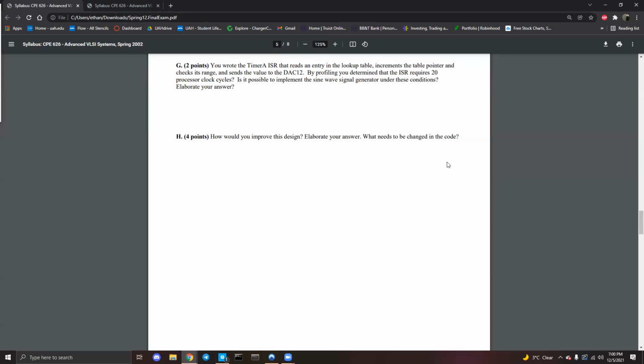You could also implement Nyquist's theorem by just literally taking 2 samples per period. And then you can say, use DMA to transfer samples from the memory to the DAC12. So that just speeds things up even more. Why use an ISR? Well, you can just use hardware that exists solely to make things faster when it comes to pulling stuff from memory and shoving it somewhere else. Memory manipulation is the DMA's bread and butter, and it's very, very, very fast at it. Much faster than an ISR could be. So you could make this even more ridiculous by using the DMA. You could probably triple, quintuple the speed and resolution of the signal.